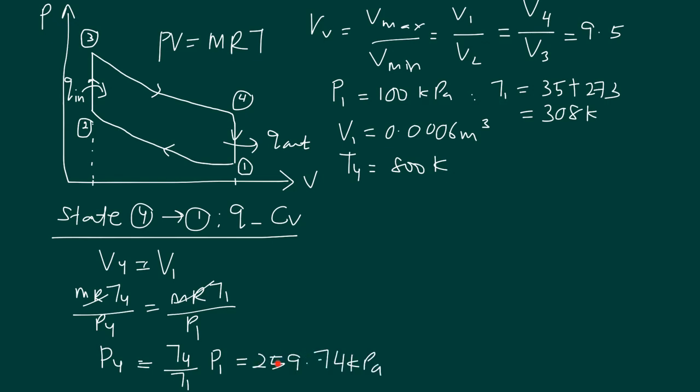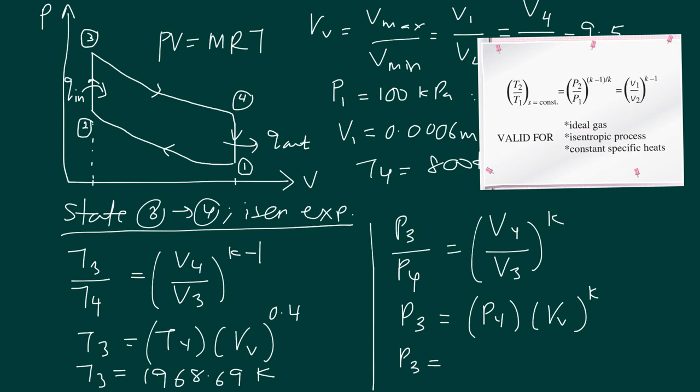now that we already have the value of P4, we can substitute into these equations and try to solve all the temperatures at all states that we need. Alright. Now you substitute your P4 value into these equations and times with your compression ratio, and finally you will get 6072.28 kilopascal. So as you can see in this PV diagram cycle, this makes the highest pressure over here. Right?